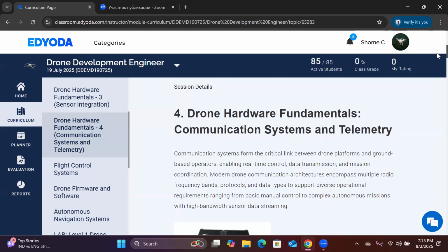And this radio frequency based communication system is based on a certain spot frequency and an appreciable bandwidth. Say, if we talk about the ISM band, we take 2.4 gigahertz as the secured frequency for communicating between the communication module and the communication box. So 2.4 gigahertz will be based on a certain bandwidth. Generally, in a narrow channel-based communication system, we take 10 megahertz, 20 megahertz, 40 megahertz as the channel bandwidth.